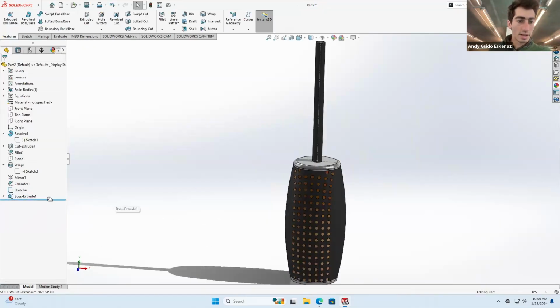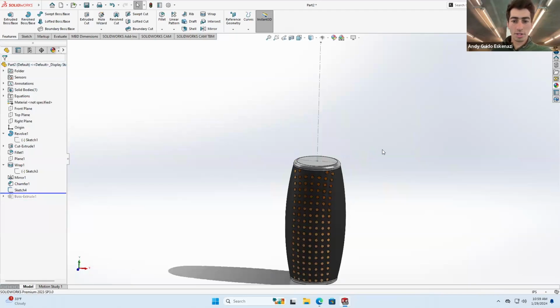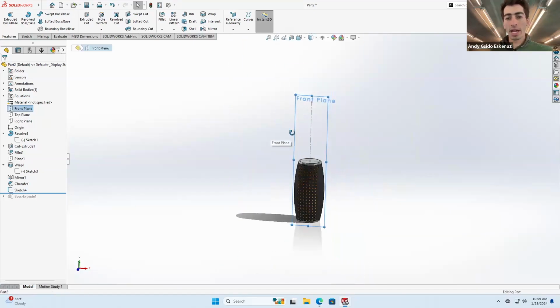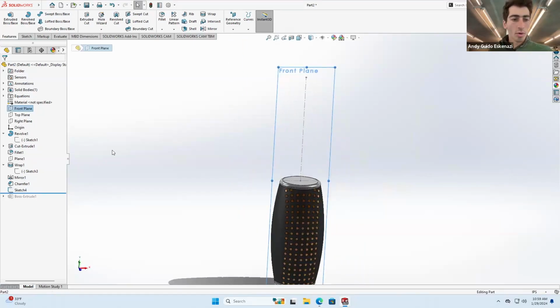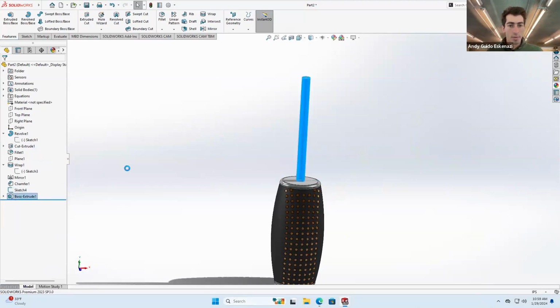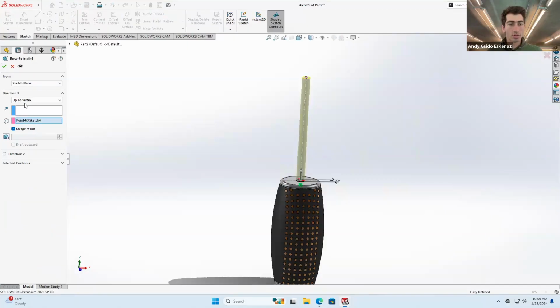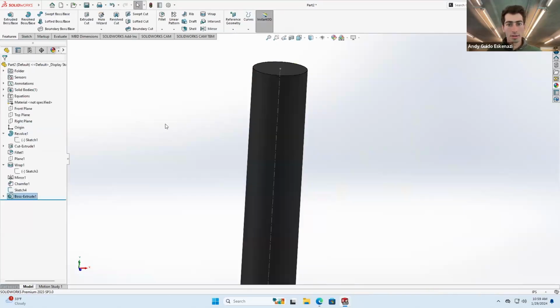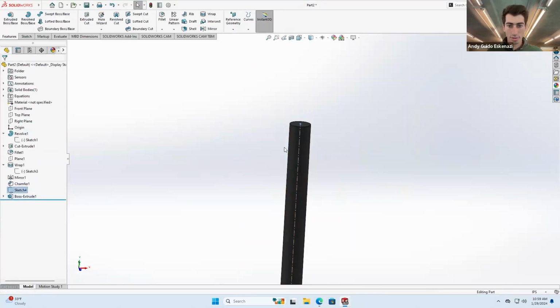So again, I created for the next step. For those of you that reach this step, it is to create on a plane in the front plane, which chops this in half, just a sketch, which in this case is sketch 4, which is just a line that goes all the way from the middle to the top by the amount that you want to extend the, how you call it, like the arm of the screwdriver. And then you make a boss extrude where the command that you're using is the one that's called up to vertex because I'm selecting that point over there. And I can hide this sketch, but I don't need it.